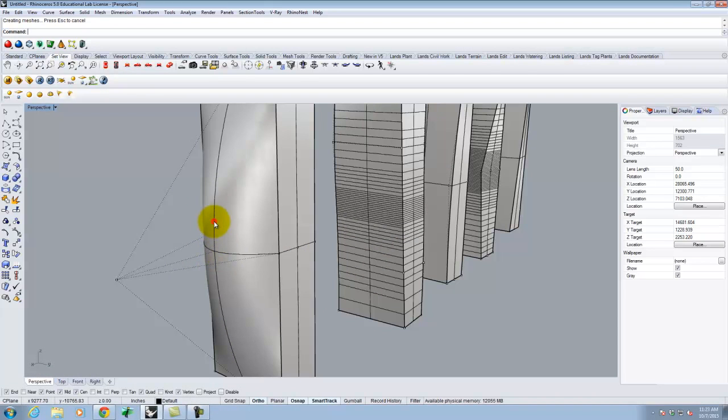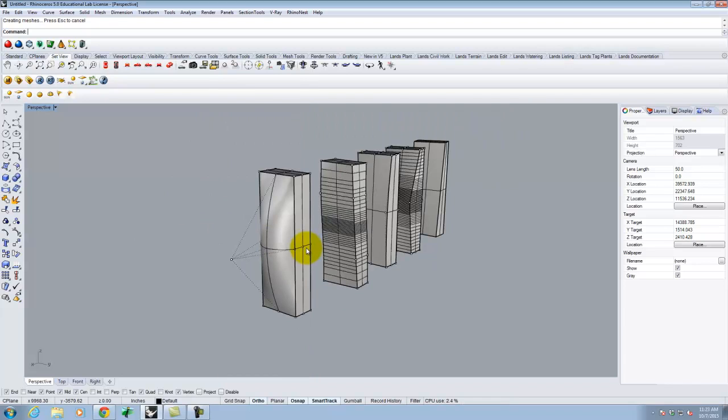Okay? This bulge is not something that I can roll flat because it has curvature in both directions. It's kind of like thinking about an orange peel. When you peel an orange, you can't have a flattened peel without having a bunch of cuts in it. Does that make sense? It's like a globe, right? And so this is a very difficult shape to make if you were going to laser cut it. These shapes are actually very, very easy to laser cut because they're this ruled surface.